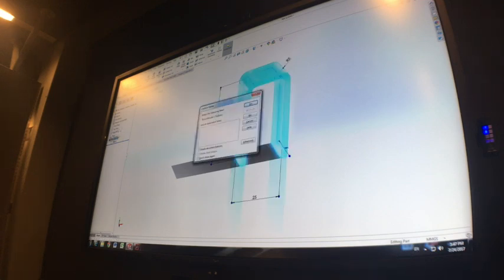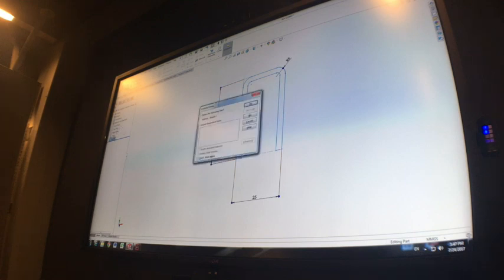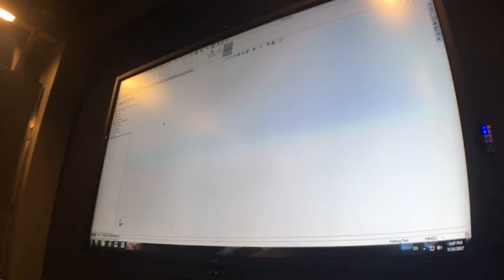I'm going to roll this back. I'm going to just start this from scratch again so that we can get the basics of setting that sketch up correctly, and that was using the offset sketch. What we'll start with is a sketch on the front plane. So click on that front plane in your feature tree and click that little sketch icon, or click on the sketch toolbar and click sketch here in the top left corner.